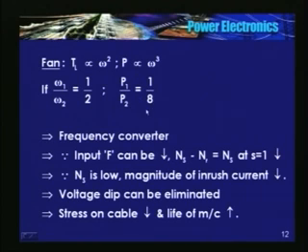See, there is a significant reduction in the power being consumed if you reduce the speed of rotation. 1/8, a significant reduction. So you are trying to achieve both, save energy as well as regulate the output discharge depending upon the process requirement. But then again, at what cost? Nothing comes for free.